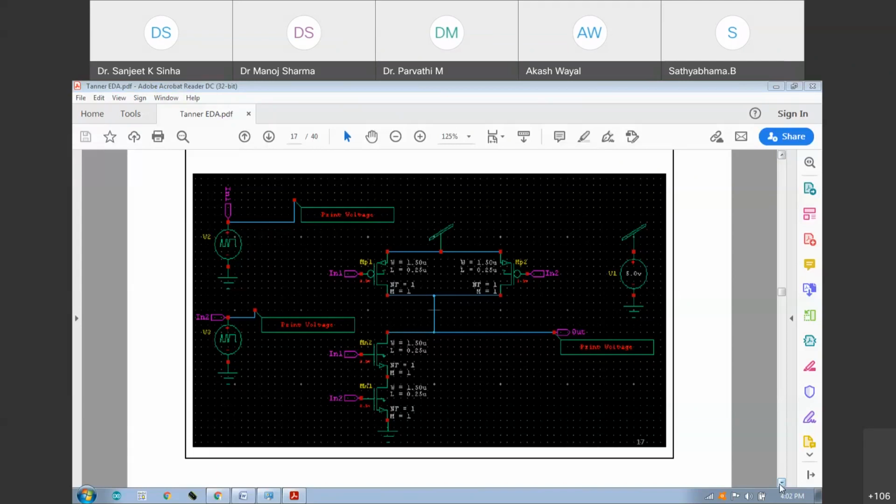The first upper one, the PMOS, is having A, B. You can see this 1 is A, this 2 is B, this 1 is A, and this 2 is B at NMOS side. And this particular VDD is coming in the same way, whatever we have considered for the inverter. And once you simulate this particular NAND gate, then you will have the actual output. Go for next.